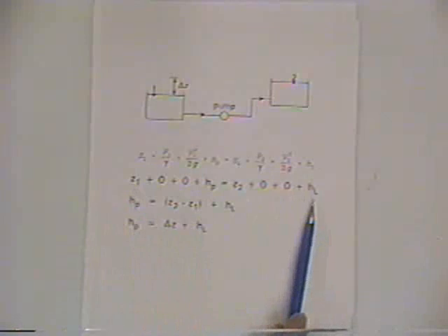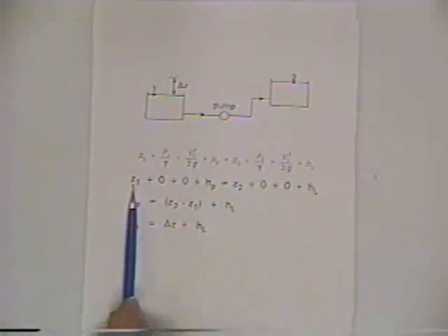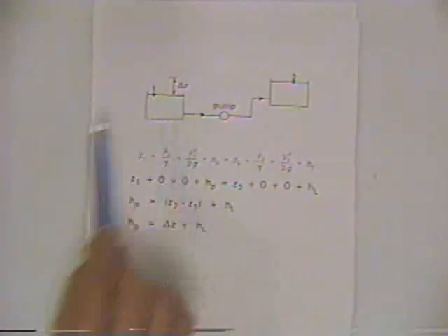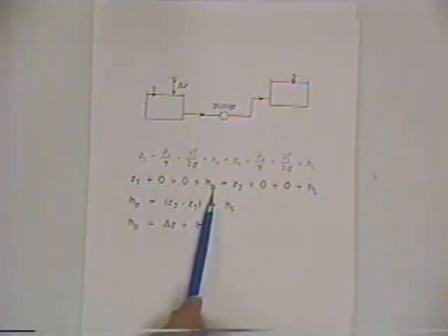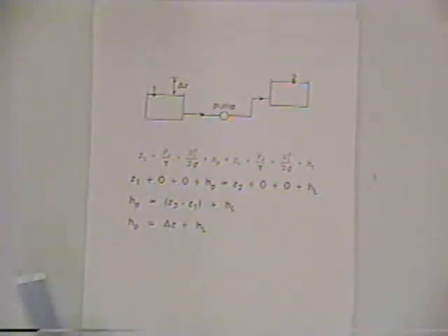We substitute in the terms as we've done already. The Z we draw through the water surface and the downstream side of the pump. The pressure head is 0, we're back to using gauge pressure again. The velocity head is 0. The head provided by the pump.